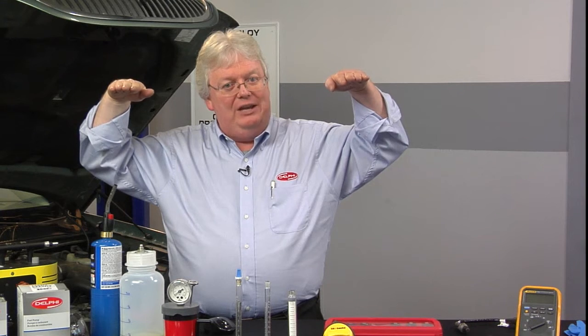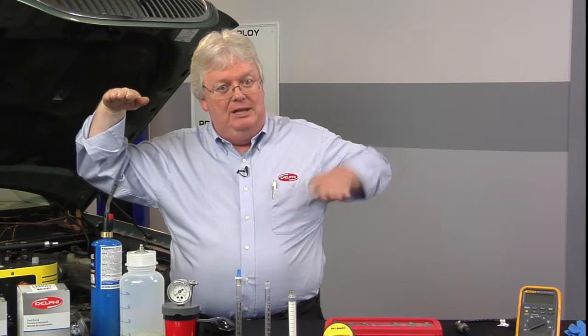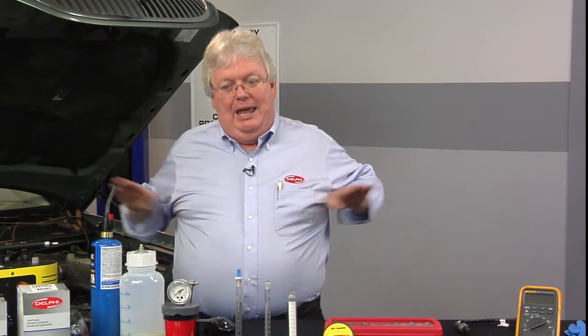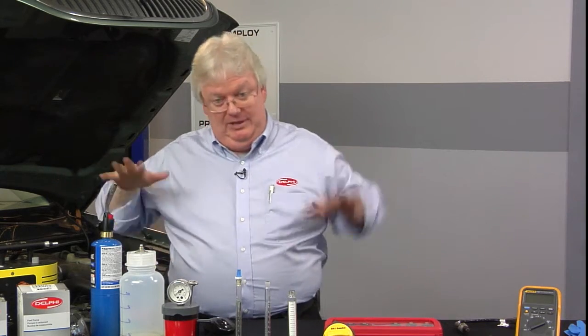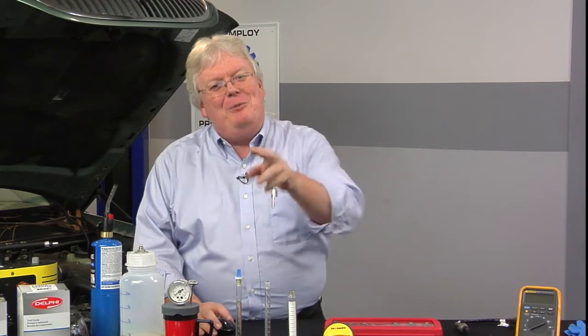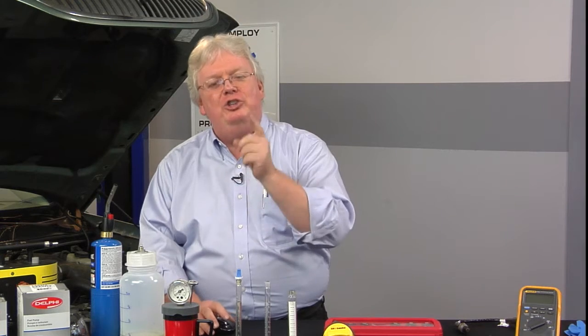So air-fuel ratio, 14.7, 16, 12, and lambda, 1, 0.7, 0.9, or 1.1, 1.2, or the voltage of an O2 or the current of the new style O2s go with the air fuel. Hope that little analogy with the hands helps you keep it in really good long-term memory, no pun intended, so when you look at these PIDs, ba-bing, you know what's going on as you drive that car or run it in the shop at idle.